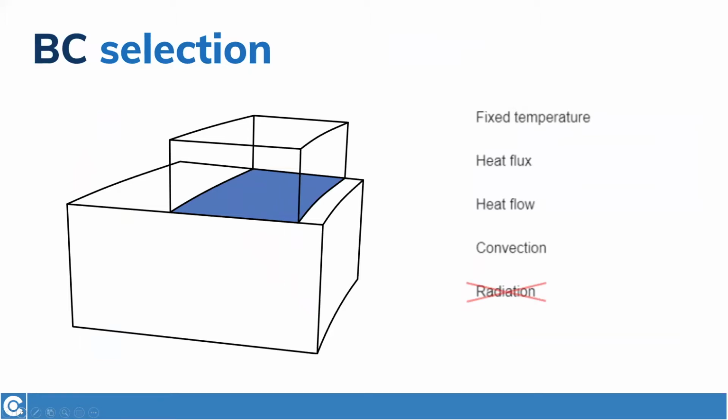In version 2.7, we have simplified the boundary condition selection in templates and from CAD approach by enabling only the relevant conditions to be selected. Previously, all available existing boundary conditions were up for selection, but now you cannot select fundamentally incorrect conditions, for example, radiation on the contact surface in between two steel parts.